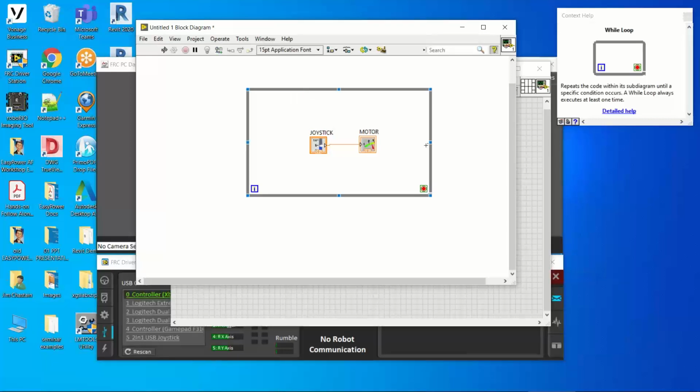Okay, the while loop is characterized by this orange dot. If you hover over it, it's called a loop condition. The word statement for this while loop is: repeat the activity inside this rectangle until the loop condition goes true. All right, so right now, if we were to do something with this, we'd know it's in the false condition.